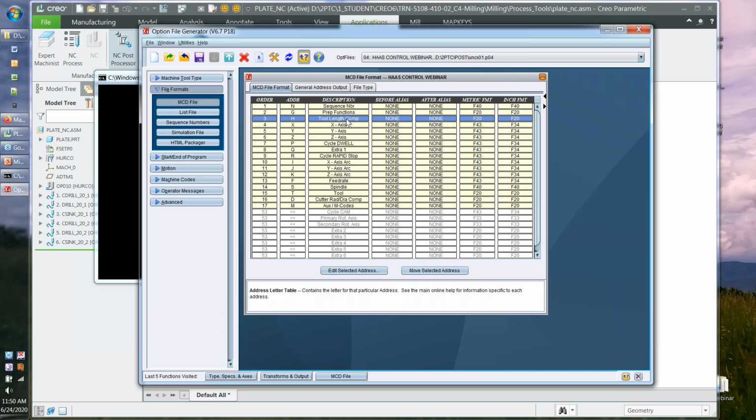The word being associated with the number is the H value. The prep code that is G43, which is most typically output for this, we handle that in a different place. That's not the word. It's like we're talking about what things connect with. The same being said, if we get down here to the S word, well, what is that? That's going to be your Spindle command. This is where you make those